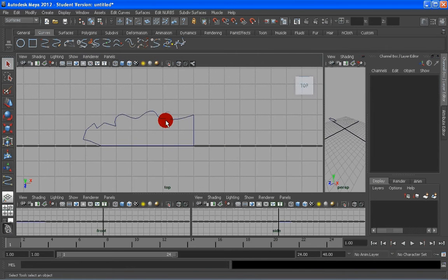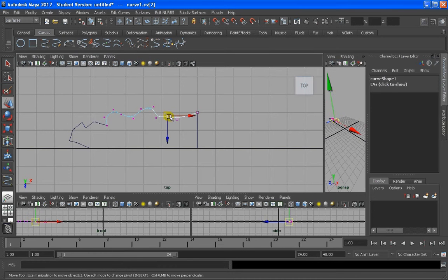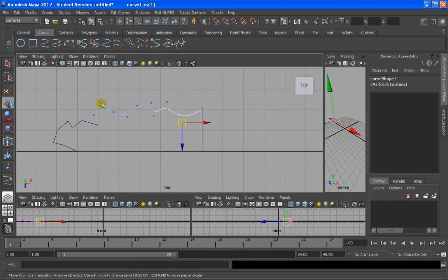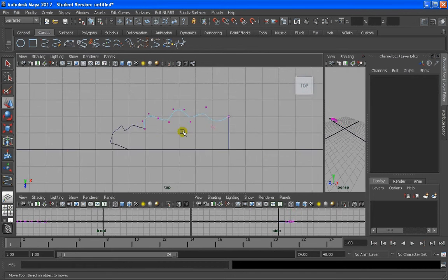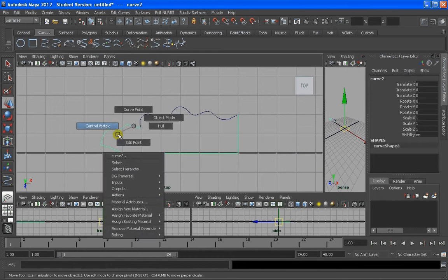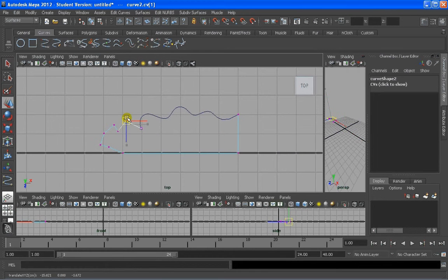So as you know, this could be a section of what I'm gonna do, the revolve of a kind of a wheel concept. So I can go here and right click and control vertex if I want to move, pressing W, any of these points specifically. Of course, this is quite without any rigor, but you see that as I'm moving now, I'm probably giving some type of detail that is more likely to fit with what I want. So that's very convenient. I can also go here and do the same, control vertex, and move these guys.